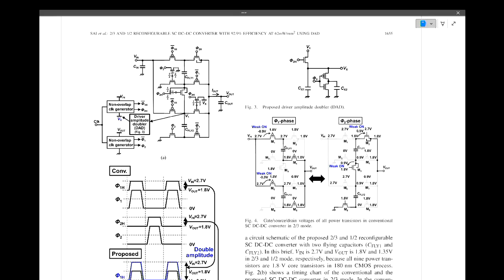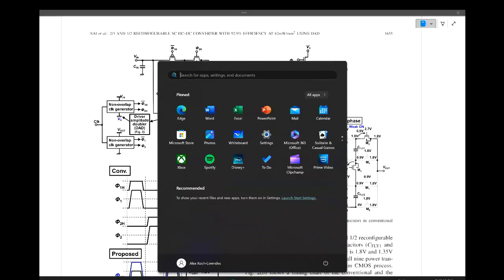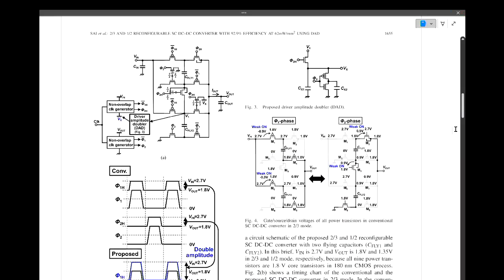The reason we use this is we can fabricate this on a chip. It's not like some big bulky external thing, which is very inefficient. I mean, you can have inductors on chip, it's just they're not nice. What you've got to do with inductors on chips, because they're very small, is switch them at really high frequency. If you switch at gigahertz or something like that, you get a lot of switching losses, and that is not very power efficient.